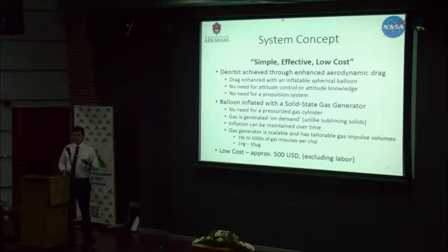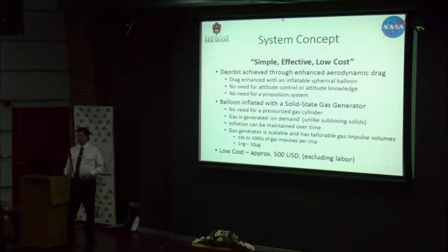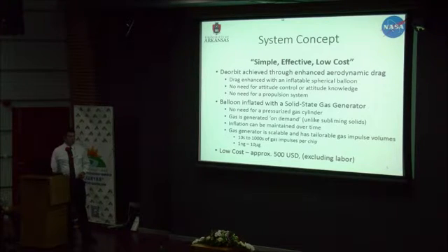Basically, it's a chip, it's a MEMS device, and there are individual gas wells that we deploy. They can be tailored to hold anywhere from nanograms to micrograms of material, thereby generating nanograms to micrograms of gas. And we can integrate tens to up to thousands of wells on a chip. So the design is very scalable and tailorable for any application.